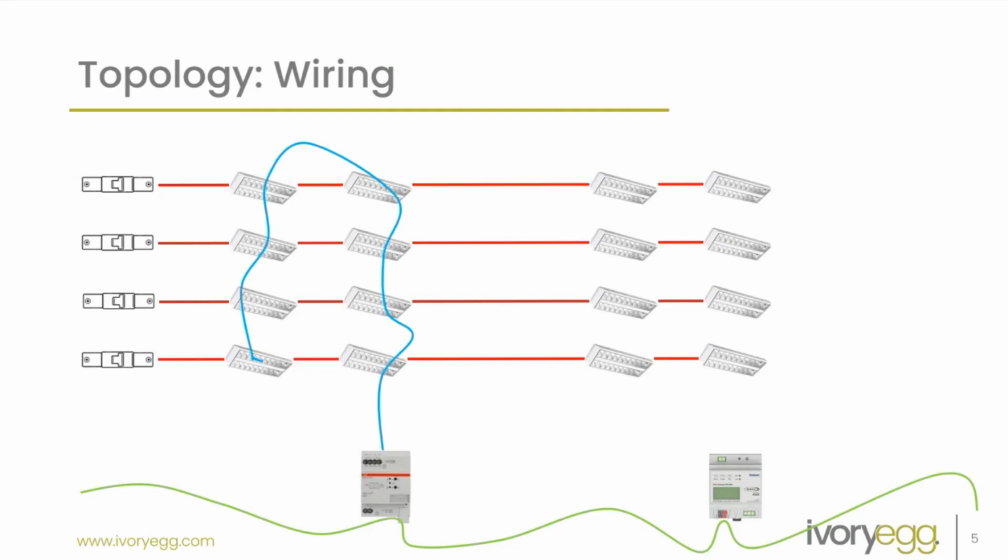So what we have here is our Dali wiring. So that's the wiring I talked about, where it can be 300 meters. It's 2 wires. We can do a daisy chain or star, as you can see in the second part, but we can't create the loop anywhere. You'll notice nowhere I've created the loop. So once we've got that configuration, we've got all those fittings, irrespective of what circuit they're on, in the same Dali universe or network.